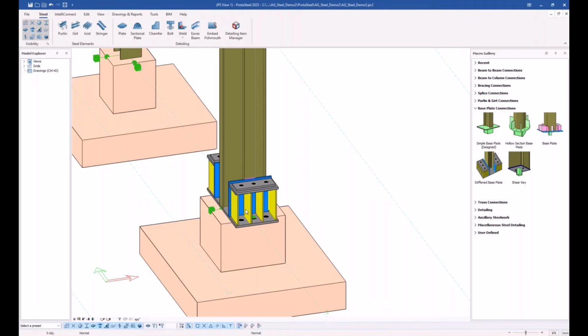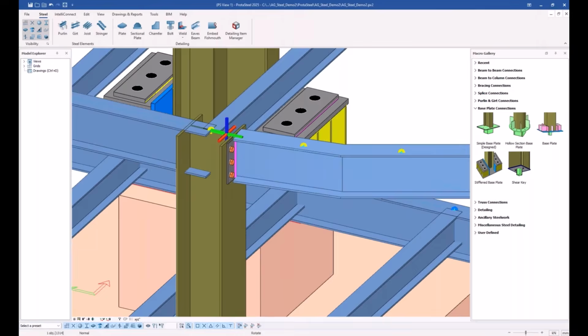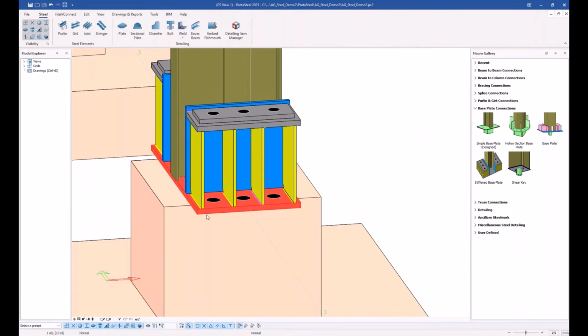This connection consists of base plates anchored to the concrete foundation through bolts, which are about to be inserted in a minute. These bolts are extended to a steel chair, like this, steel chair's configuration. The purpose of this is to concentrate the plastic strains mainly in the extended region of the anchor bolts, so that the rest of the components remain elastic, particularly under seismic loading, of course.